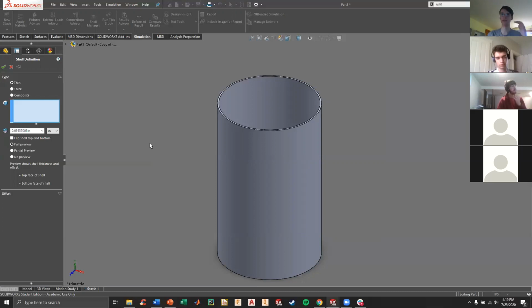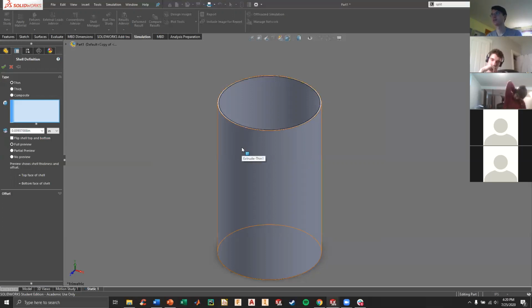Because if you look at a 3D model, you're going to have millions and millions of elements, whereas a 2D model is not even hundreds of nodes, which are the points. So each 2D element will have maybe 10 nodes, which are essentially vertices all around it. And then a 3D element will have, I guess, 4 of those. So you have 40 nodes per element, of which there are millions if you're doing 3D. So SolidWorks offers simplifications in the form of turning it into a 1D beam that's just node line, node line, node line, or a 2D shell, which is the same kind of thing. They're still elements, but they only have 3 nodes, and it's just a 2D mesh. There's no 3D aspect to it.